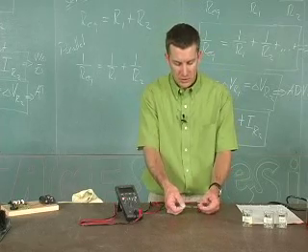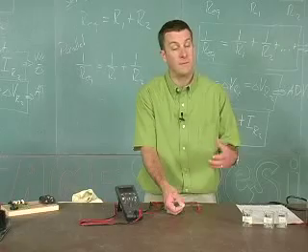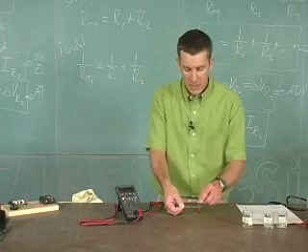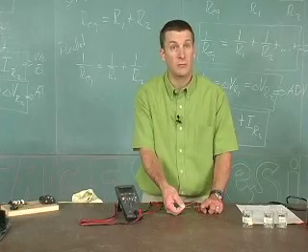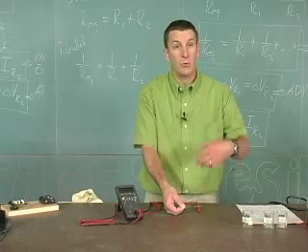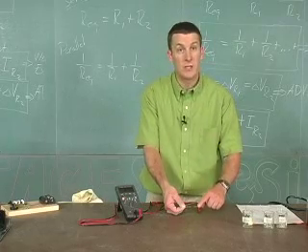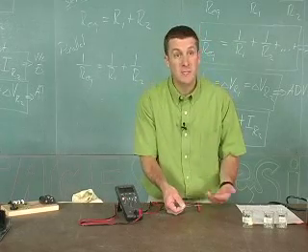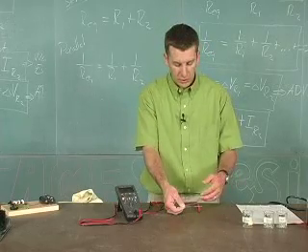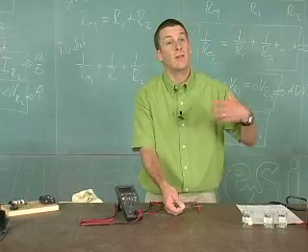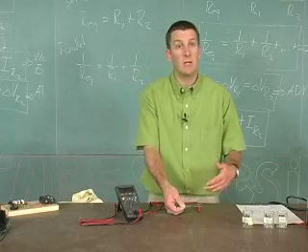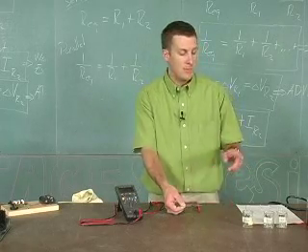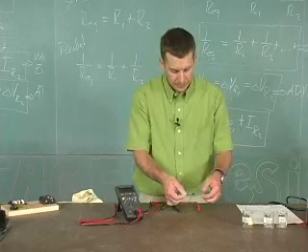Now, I want to really focus on the fact that these resistors are devices where one is rated at 150, and this one right here is rated at 1,000 ohms. So we're talking 8.5, 9 times more resistance is provided by this resistor than this one. Yet they're the same size. Well, that has to do with the material that's inside and the resistivity. They're both at room temperature, so it's the material that it's constructed of that produces these different resistances.